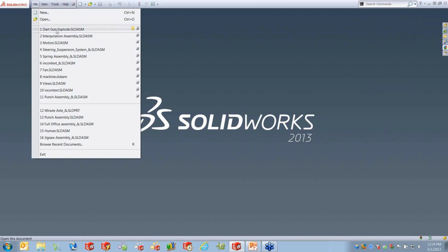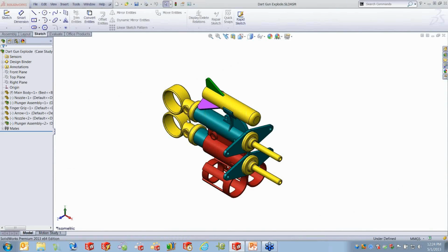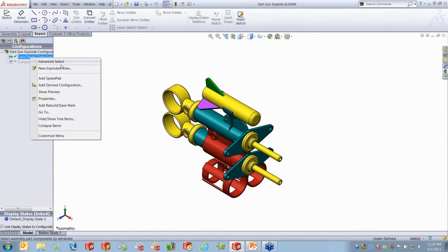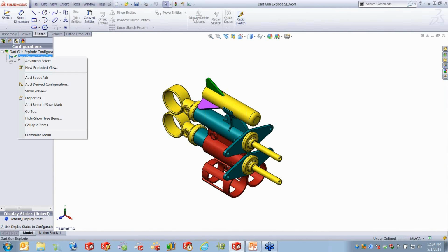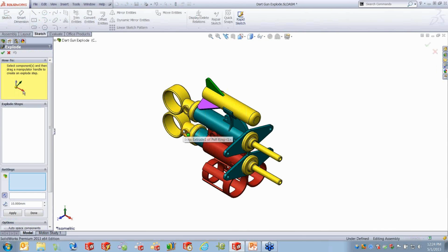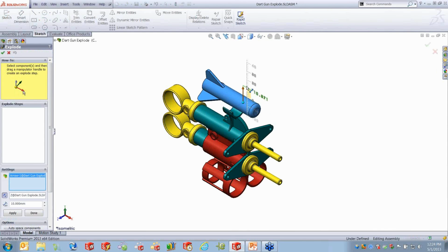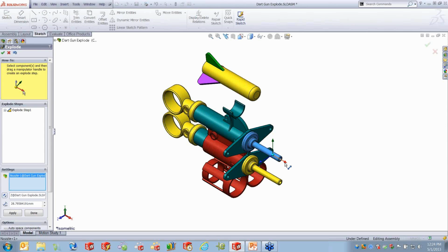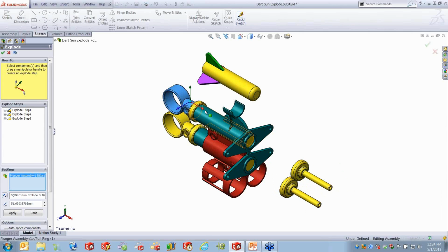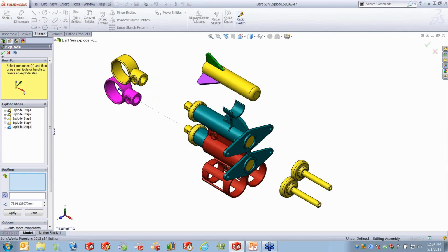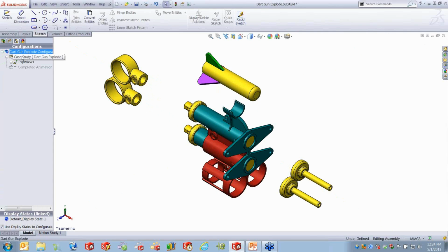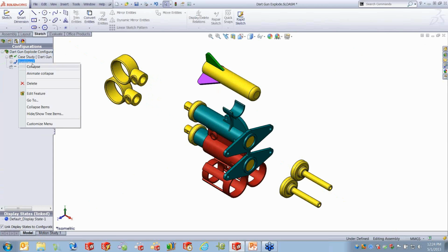We're going to start out with maybe a concept that you've utilized already. We have the ability in SolidWorks to create an animation. The animation that we create can be done through exploded views. So if I decide I want to explode this thing out, I can start to drag this, and each step is captured. We know that that happens, right? And when I decide that I'm completed with this, the software in SolidWorks gives us the ability to animate the collapse or the explode of this.